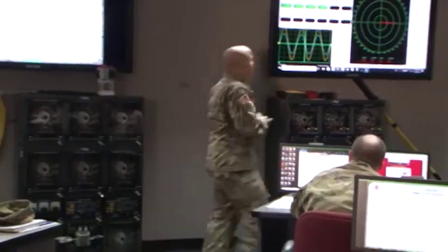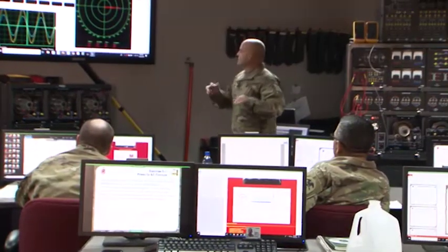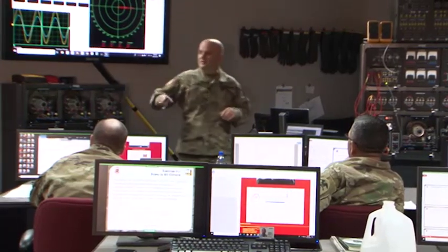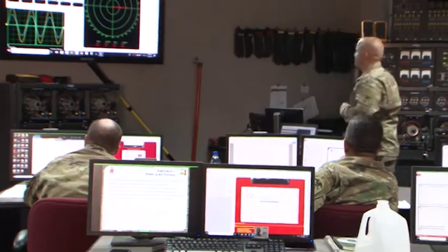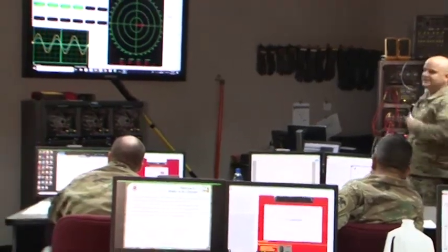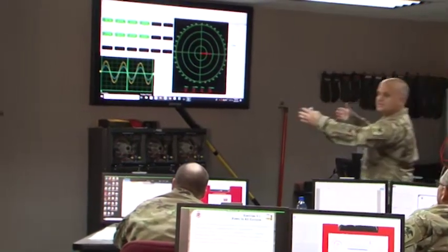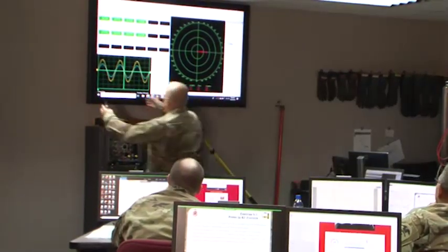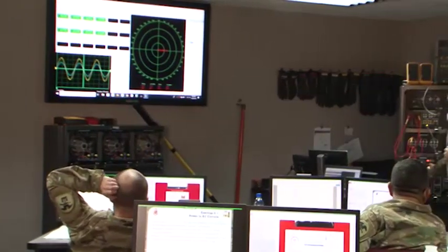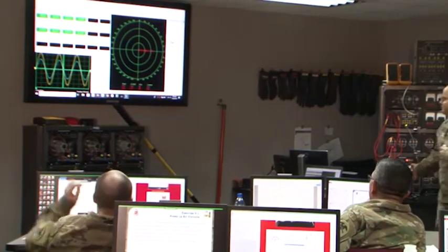Okay, so now based on the proportionalities that we know from Ohm's law, if I dial down the voltage, what's going to happen to this voltage vector? Shorten. It's going to shorten. What's going to happen to the current vector? Shorten. Cool, let's see if this works. Boom. Now look what's happening over there on that oscilloscope at the exact same time. The same angular relationship exists. All this is the same. We're not adjusting the frequency. It's 60 hertz from the power supply, but now we're seeing these differences, right? Cool story.